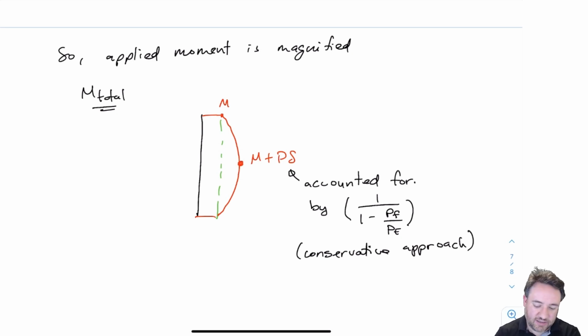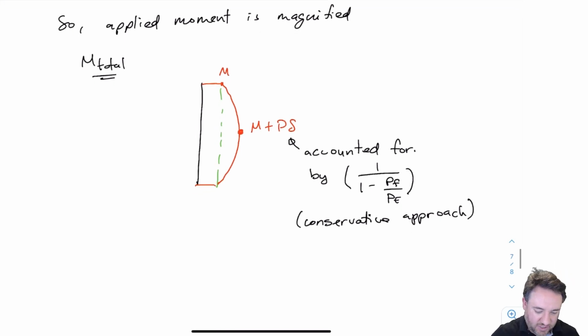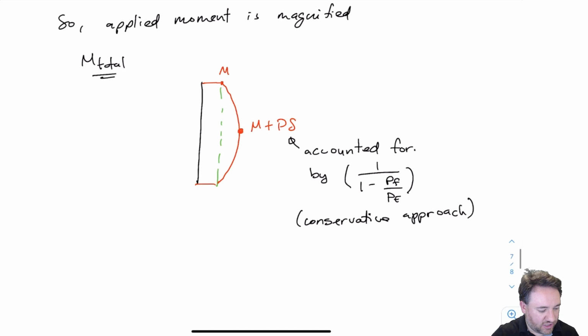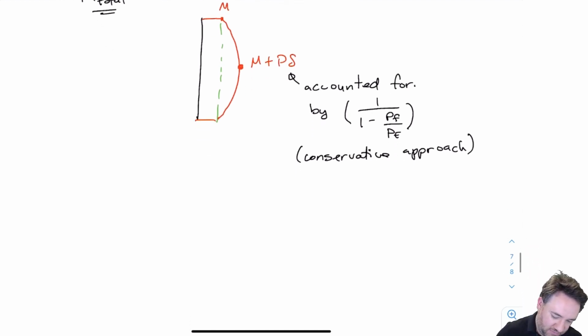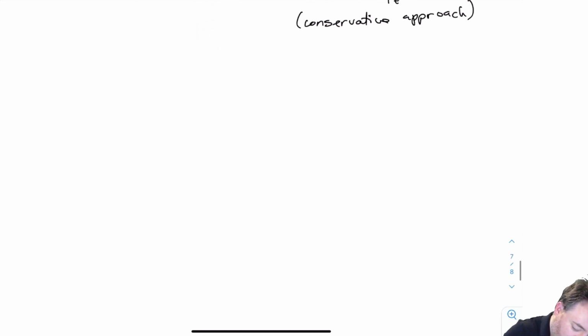You'll notice that it has no indication here of what the actual displacement is that we're accounting for. Okay, so there is another equation that we can use that's a bit more accurate, which I'm going to show in a minute. But that equation is more aligned to this second kind of P delta effect, which is the P big delta effect, which we're going to talk about now.